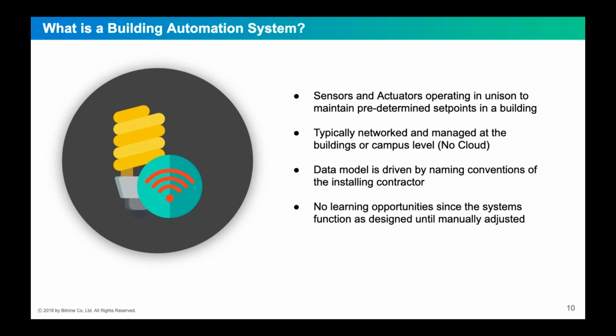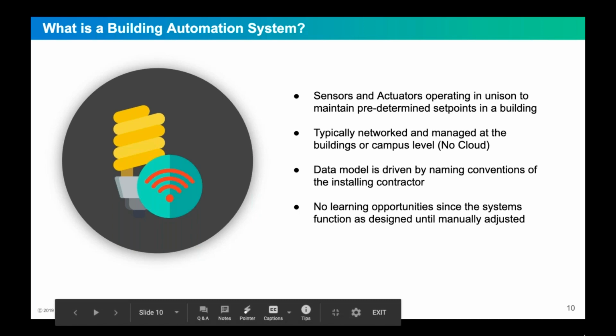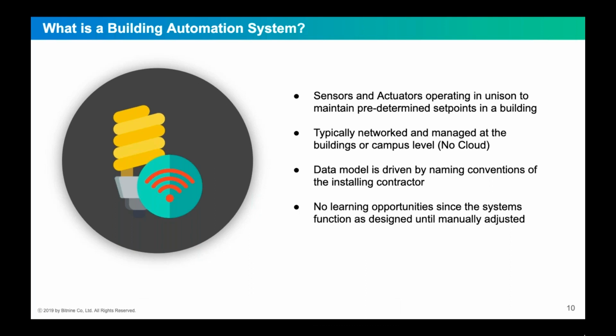Building automation systems are very similar in that regard, in that there is a network of different devices within these commercial or government buildings. A key difference here is that our customers are primarily dealing with hardwired networks. While the industry has moved towards IP-based controllers, where you're dealing with Cat5, Cat6, Ethernet cables for communication, a lot of our customers have installs where they're using a serial connection, like a two-wire connection between these things, and they're daisy chained in line. So you don't have all of these efficiencies. In a lot of ways, home automation is a little bit ahead of building automation systems.